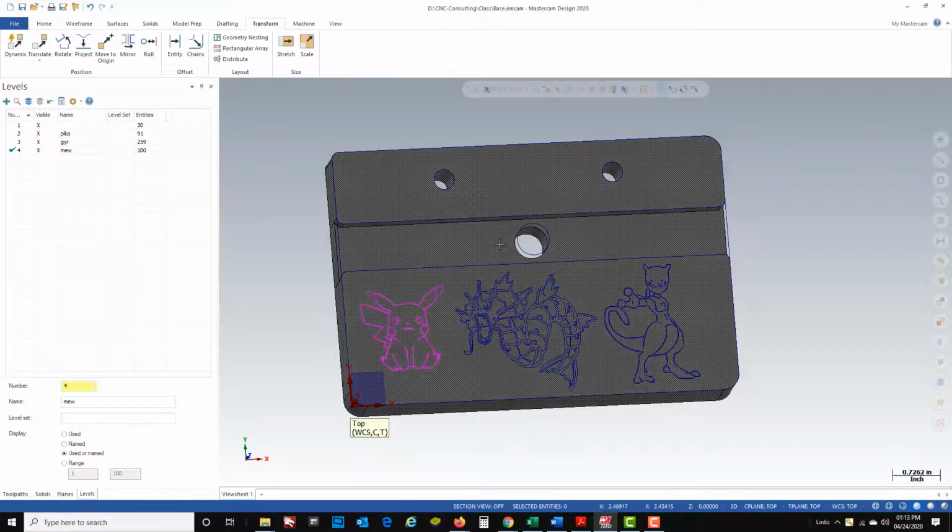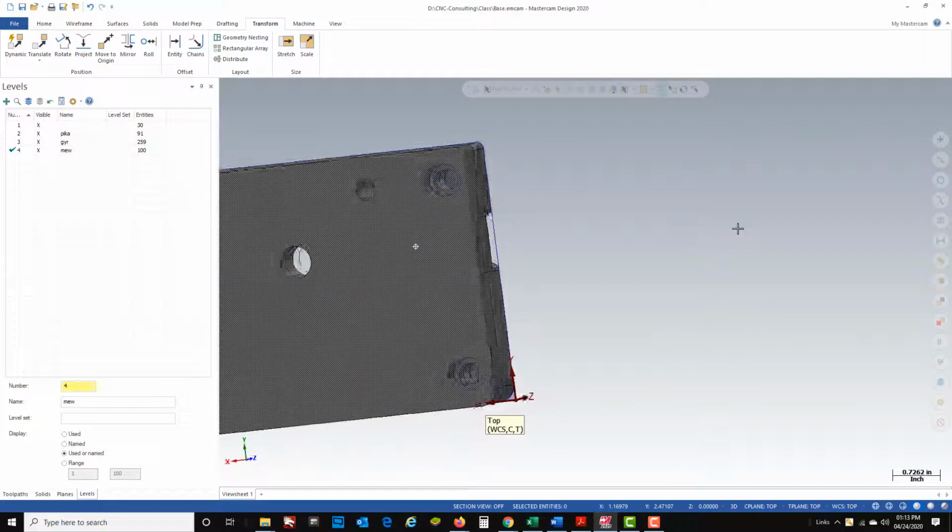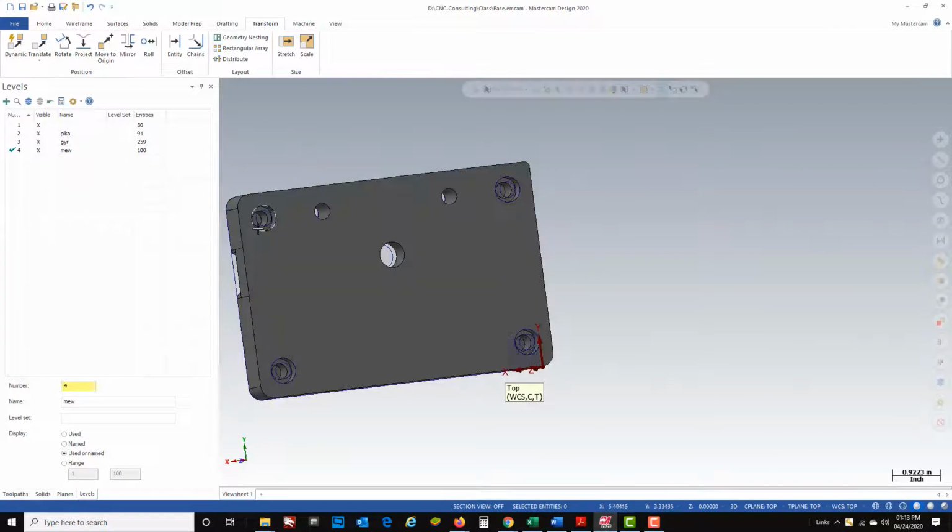The way that I'm going to machine this block is I'm going to load it up into a vise and cut the backside first. I'm going to face it, put in all the holes, add a chamfering program.